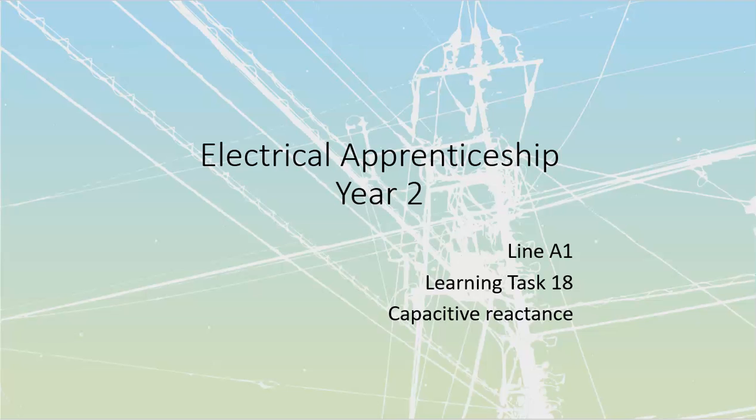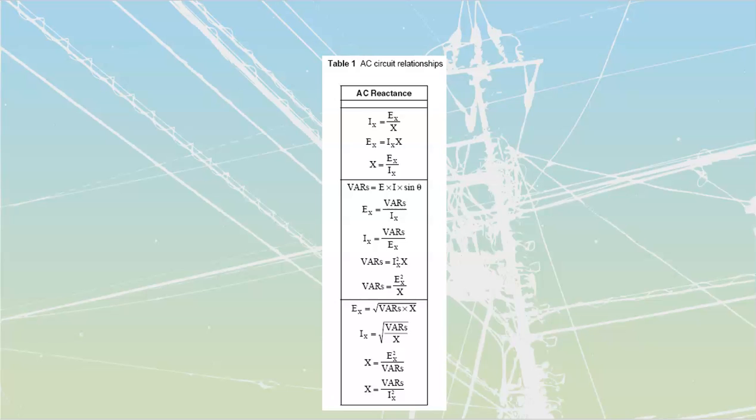This is actually a really big deal to us as electricians, knowing how stuff changes as we change over frequency, because when we change frequency, it changes all of our components. And we'll see that inside of our XL as well as inside of our XC, our capacitive reactance and our inductive reactance, because both of those formulas have to do with frequency, which means when you buy a European motor rated for 50 hertz, or an Asian motor rated for 50 hertz, or some of the South American motors that are rated for 50 hertz.